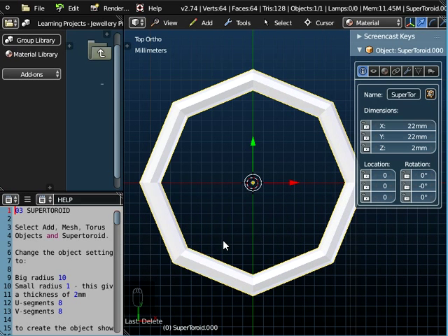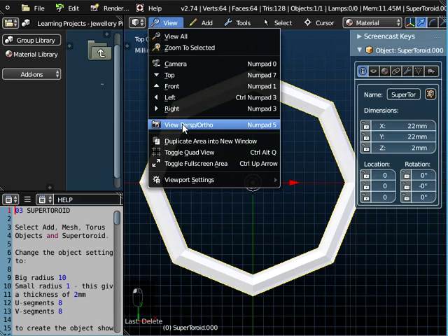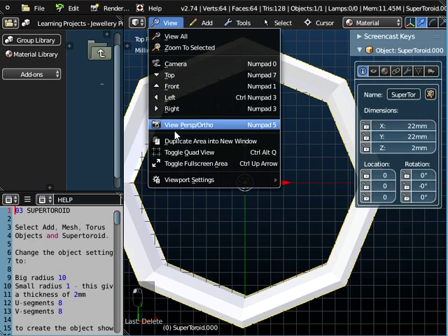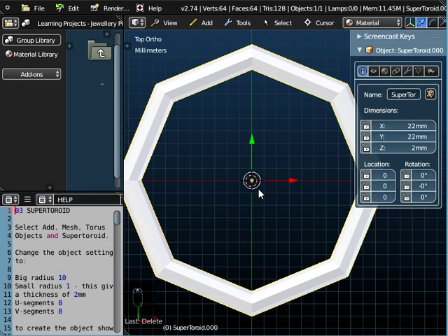You don't see it in perspective. You don't see the back of the object. You see a much cleaner view of it. So that's just a toggle from perspective mode. Here you can see the back of the object in this case, so any measurement we take there won't exactly be right. So it's always best to switch to ortho mode.